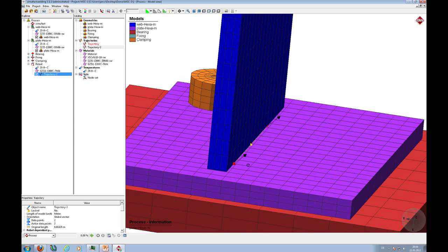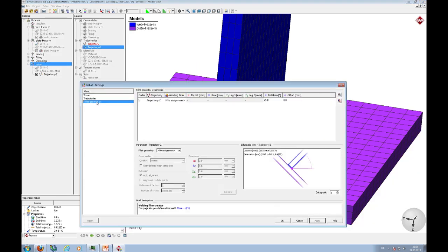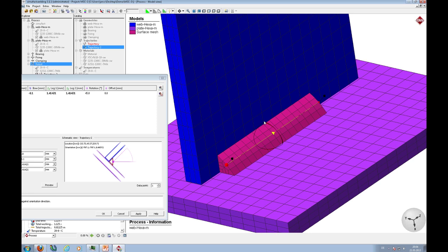If I have such, for example, a gas metal arc weld, I will have also a fillet. And for that, we also need an additional finite element mesh for the fillet. I can create one using our fillet generator. I can say, generate one, propose me some values, have a look in the preview, and I will get such a fillet.